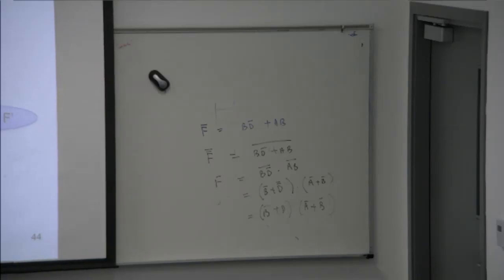Now in the black color, A is not changing and B is not changing, and we have a 0. And in the POS expression, we complement it. Can you see here? This is 1 and 1. So what do we get? A bar plus B bar. Do we take 1 in true form or complemented form? 1 is in complemented form for the POS expression. And 0 is taken directly if you want it without converting into SOP expression.